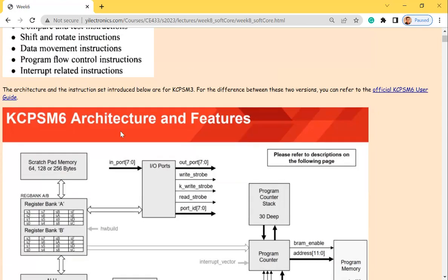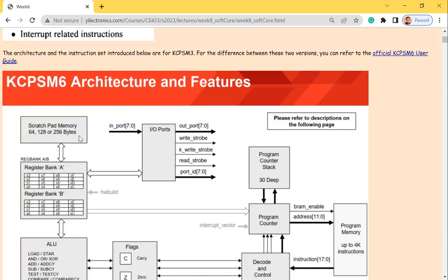So actually, you put this one in like an instance, right? You declare it in your Verilog in the top module as a core, and you rename it as whatever, core 1, core 2. And then you make the connection with the top module's switches, LEDs, seven-segment displays. So the output or input of the CPU will be connected to these utilities on your FPGA board. So you can use input to send signals to it, and output to verify your output.